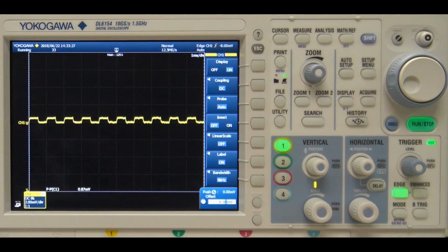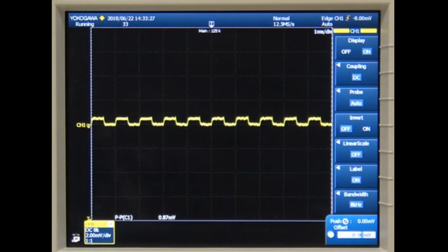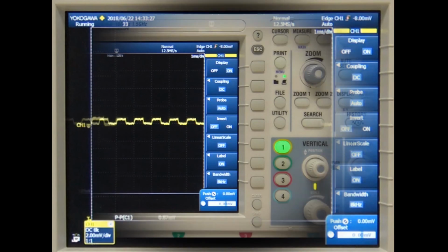What happened? My oscilloscope is a very expensive one. It has an impressive bandwidth of 1.5 GHz, but obviously I don't need this bandwidth to detect a square signal of only 1 kHz. Using a measurement bandwidth much larger than the signal bandwidth, we are just obtaining a very poor signal-to-noise ratio. Very nice, but let me show you one more trick.